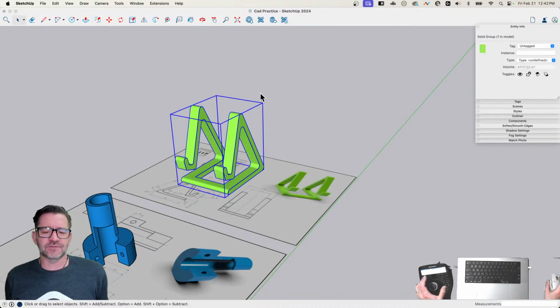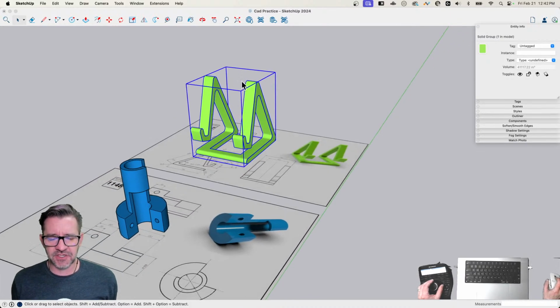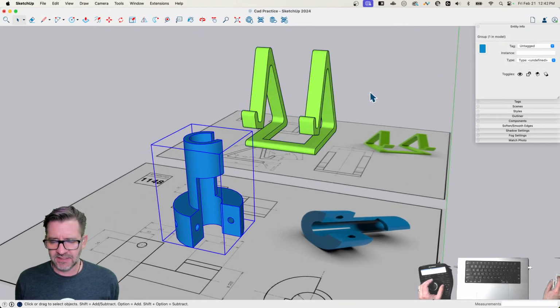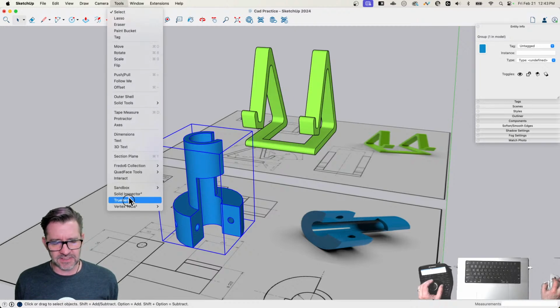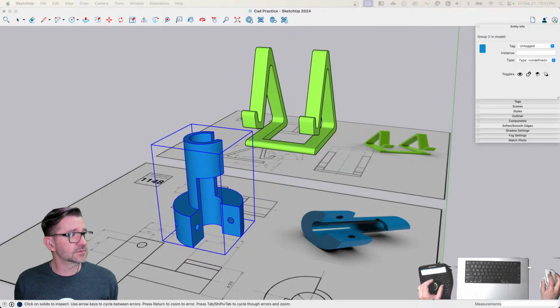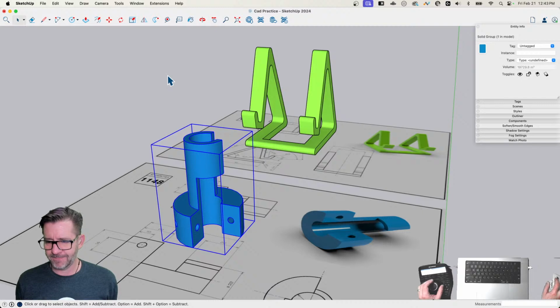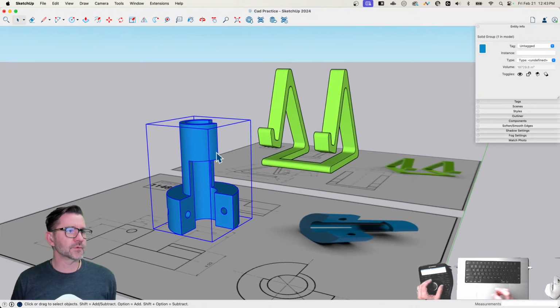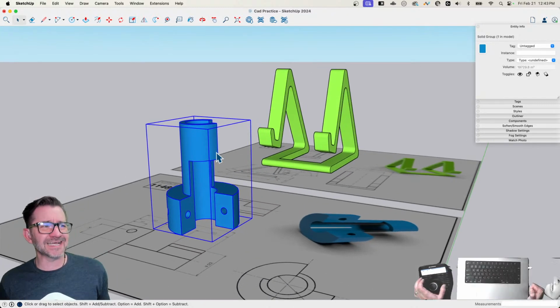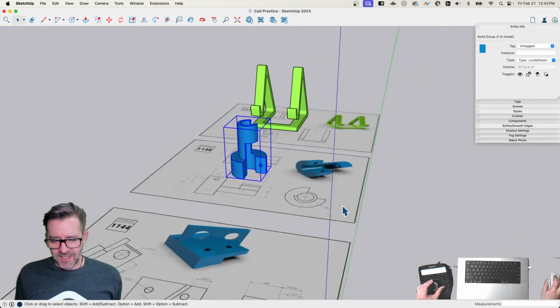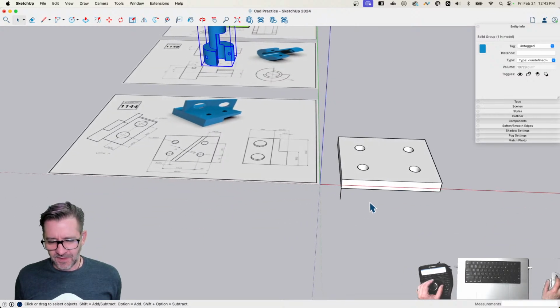There's no gravity. There's a whole lot that there's not in SketchUp, but I can figure volume, as long as it's solid. This one I picked, for whatever reason, isn't solid. So let me hop over to Tools, Solid Inspector. I have a straight edge somewhere. I'll fix that. Monster Nav says if you have the volume, all you need is the weight by volume. Right, that's what I said. Science stuff. Numbers and things.